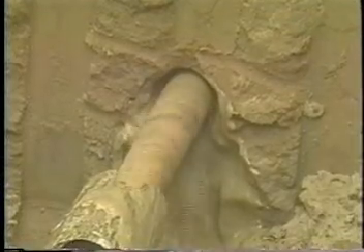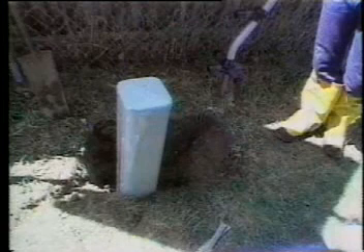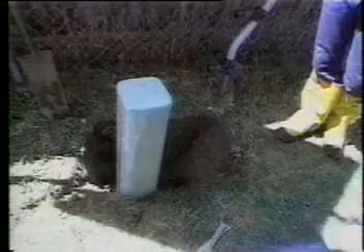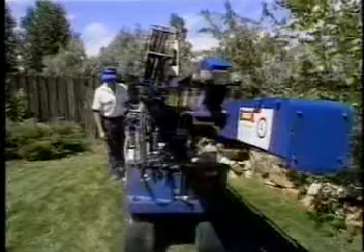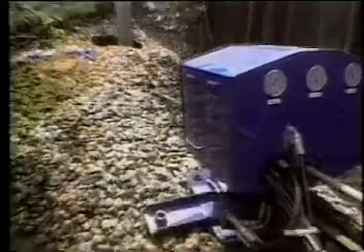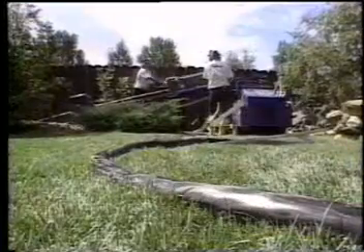Directional boring makes use of a steerable tunneling device that can travel under, around, and between obstacles and other utilities without any surface disruption. Two small pits are excavated, one on either side of the obstacles to be traversed. The drilling equipment is positioned at the starting pit and the tool head sent on its way. In this example, the cutting head uses high-pressure liquefied clay to cut through the soil as a drill pipe pushes it forward. More sections of drill pipe are added to advance the cutting head.